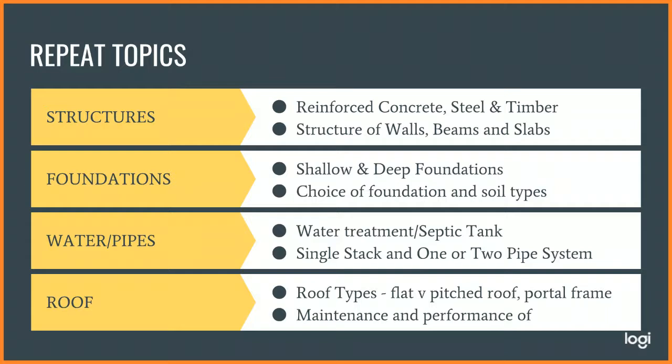For structure, they will ask about reinforced concrete, steel or timber, structure of walls, beams and slabs. For foundation, they will ask about shallow foundations and maybe mention one deep foundation, the choice of foundation and soil type. Of course, if it is a strong floor with very stable, good soil, then the foundation would be different compared to terrible ground with sinkholes, all these ex-mining areas. In KL, there are a lot of ex-mining ponds. So if there is construction of a condominium around this area, then it will definitely be different. There will be emphasis on the foundation work.